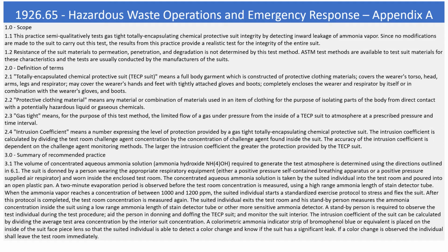3.0. Summary of recommended practice. 3.1. The volume of concentrated aqueous ammonia solution, ammonium hydroxide, NH4OH, required to generate the test atmosphere is determined using the directions outlined in 6.1. The suit is donned by a person wearing the appropriate respiratory equipment, either a positive pressure self-contained breathing apparatus or a positive pressure supplied air respirator, and worn inside the enclosed test room.